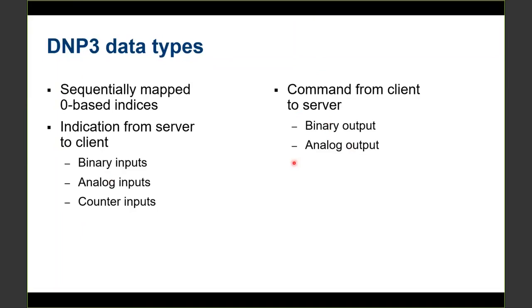So it means the breaker status of the relay I can get from the binary inputs, and send a binary output to control the breaker, so open or close the breaker.